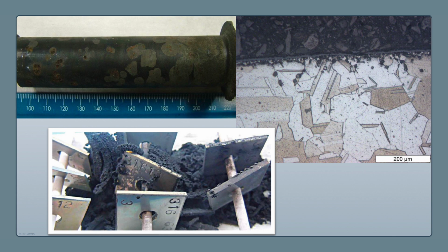Because what happens during metal dusting in the specific environment is the carbon ingresses into the steel. It then starts reacting with iron to form iron carbide, which is that cementite or cement layer. Then this cement layer further decomposes to form the graphite carbon, and that falls off as a dust.